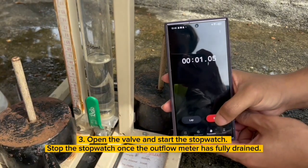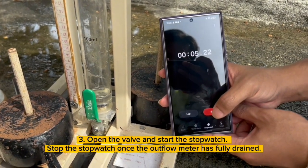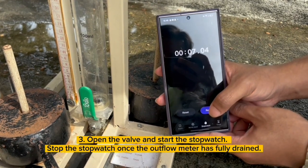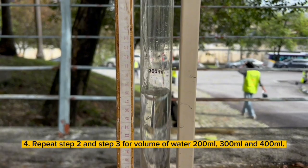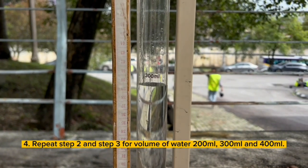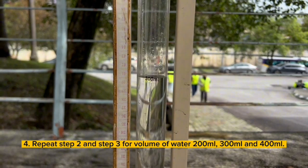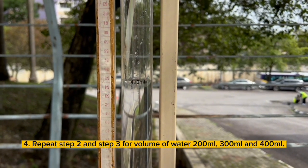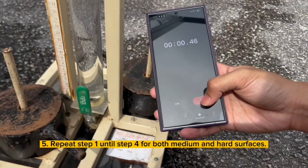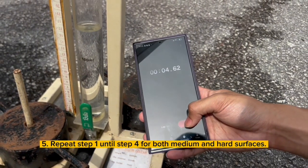Open the valve and start the stopwatch. Stop the stopwatch once the outflow meter has fully drained. Repeat steps 2 and 3 for volumes of water of 100 ml, 300 ml and 400 ml. Repeat steps 1 to 4 for both medium and rough surfaces.